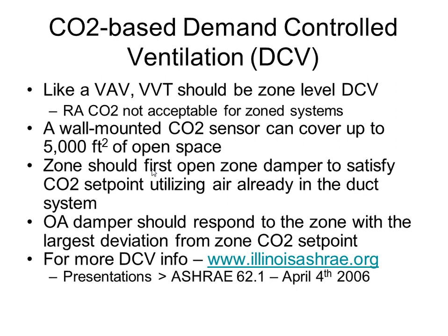So that should be your first stage, and then if you can't satisfy that way, you should open up your outdoor air damper more to get more ventilation air. For more information on DCV, you can go to ASHRAE's website. There's a bunch of codes and descriptions of the best way to run DCV, but it's pretty simple, very applicable for VVT systems. You just need local CO2 sensors.